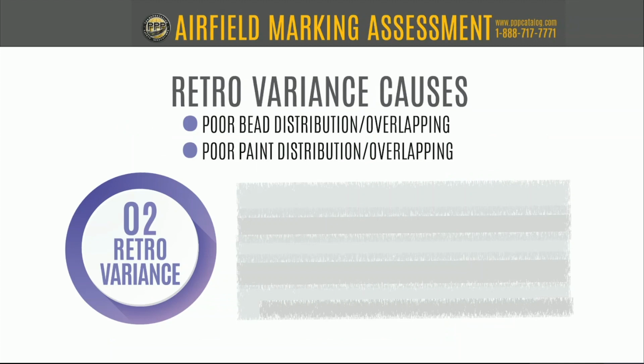However, when you have that overlap, particularly when you've got an airless system and you're using switch tips, let's say some Graco tips, what I advise you use is those yellow or gold LL or line laser pavement marking tips. Those have been designed to paint markings as uniformly as possible for pavement marking. It is not an architectural tip. Like Greg mentioned, those black tips are not good for airfield markings. Unless, Greg, I know you've got an opinion on this. You want to share that one?